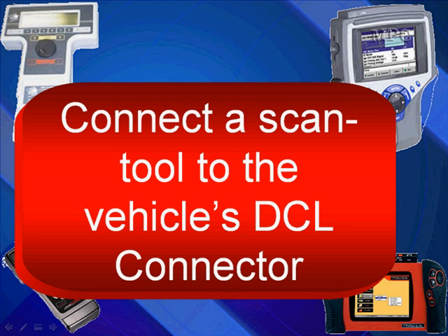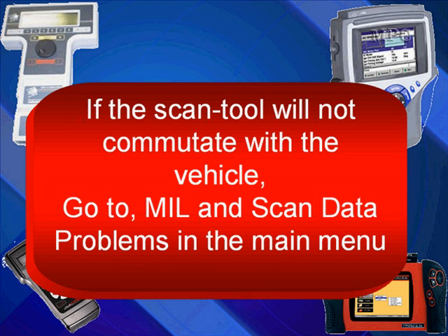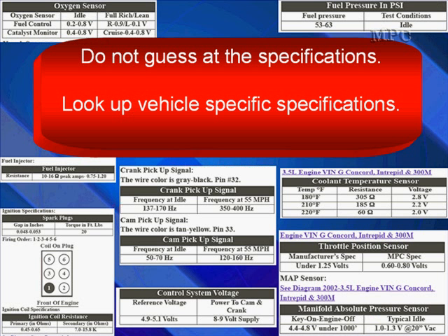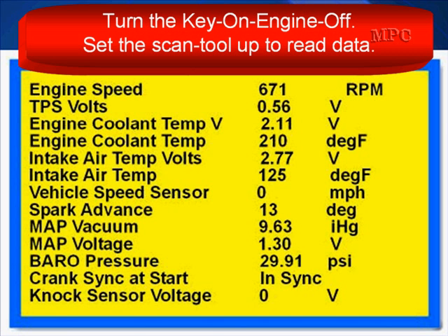To perform scan data analysis, connect the scan tool to the vehicle's DLC connector. If the scan tool will not communicate with the vehicle, go to Scan Data Problems, and that menu is in the main menu. Do not guess at specifications. Always look up vehicle-specific specifications.